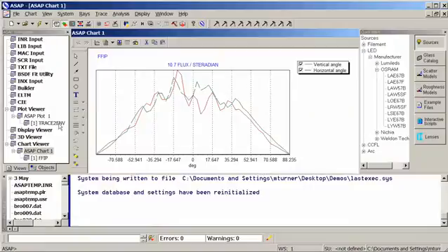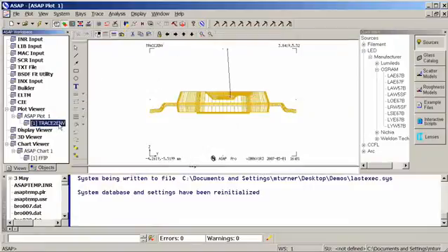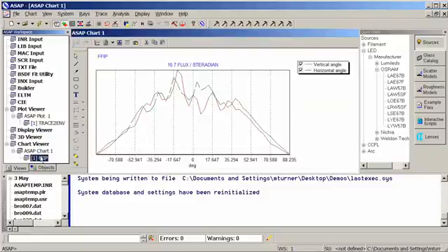Now, there are two pieces of information we see now. The first is the representation of the LED within ASAP, and you can see how physically accurate the model is. We can also look at the energy distribution plot in flux per steradian, and as we can see, it is somewhat Lambertian, limited, of course, by the small number of rays we've generated. Normally, you would want to trace hundreds of thousands or even millions of rays, depending upon your particular application.